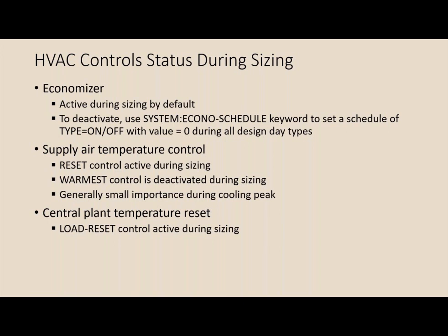So in our models, we deactivated economizers, and you can do that in DOE-2 using the system keyword called ECONO-SCHEDULE. It's an on-off type, and you just set the value to 0 during all of the design day types. So the design day period has a value of 0, and otherwise it has a value of 1 to enable economizer operation.